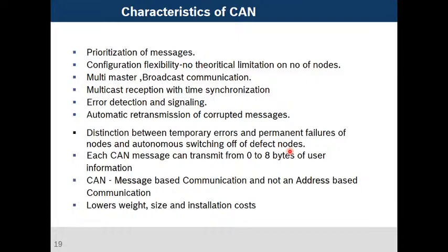Here is the configuration flexibility. There is no theoretical limitation of nodes, but practically we have a lot of limitations in a car. We cannot offer more nodes, but theoretically there is no limitation. Then the multi-master concept, and broadcast communication is also possible. Multicast reception with time synchronized communication can be done. And the main advantage is error detection and signaling.